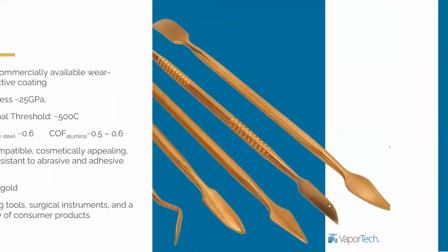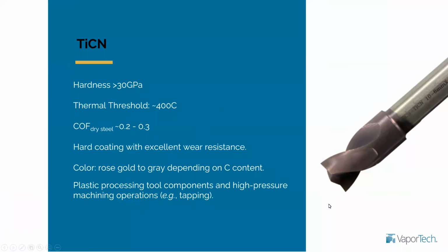You can modify that coating by adding carbon as well. That increases the hardness a little bit. Some of these TiCN, or titanium carbon nitrides, can't operate as high as the titanium nitride, but not by much, right? It tends to be a really hard coating.